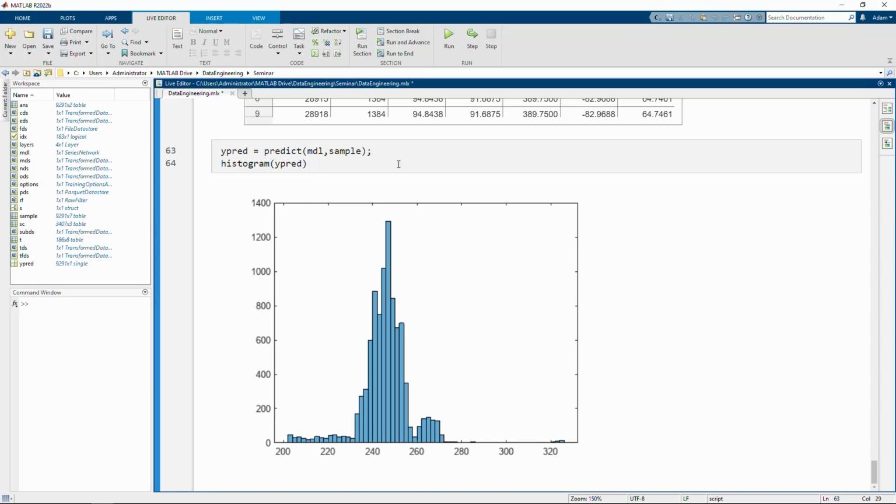Again, today we started with a big cloud of raw mat files. We went through an ETL workflow using datastores, transforms, and writeall to get that into a better format inside of Parquet. Then we used the Parquet datastore, as well as datastore transforms and sidecar files to help us subset down to only the subset that we care about and do some foreach analysis. And then we were able to train a very simple AI model across all of our data using the trainNetwork command.